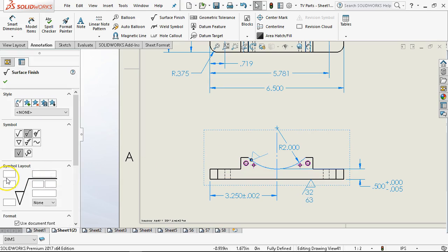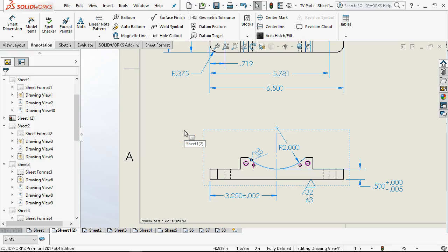And so if you put a symbol call out of 32, and my machining process gets it to a 16, but you don't need a 16, and it's actually going to be detrimental to the assembly, then I need that lower number so that I can adjust my machining process to match a desired finish. All right, so in this case, the 32 or better, between 32 and 63.